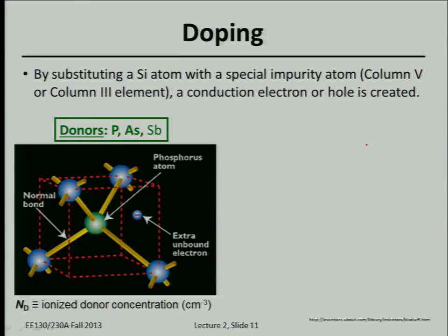Now, of course, today it is possible to change this. What we do in a modern integrated circuit to enhance hole mobility is compress the semiconductor crystal to make the spacing of the atoms closer. So it's easier for a hole to move from one covalent bond to the other, in other words, to make it easier for holes to move through the crystal.